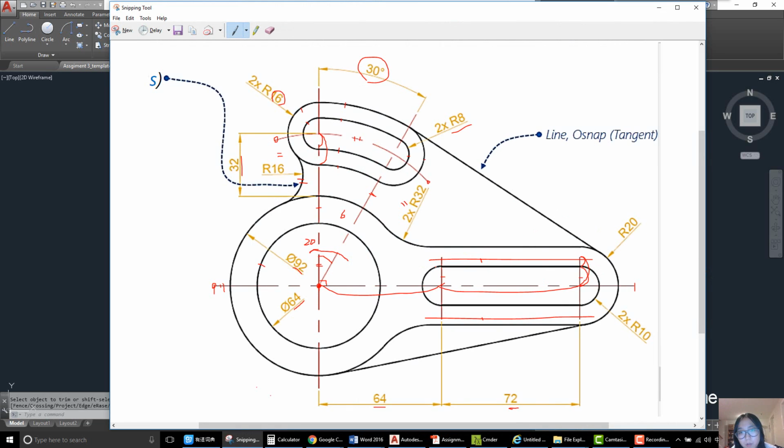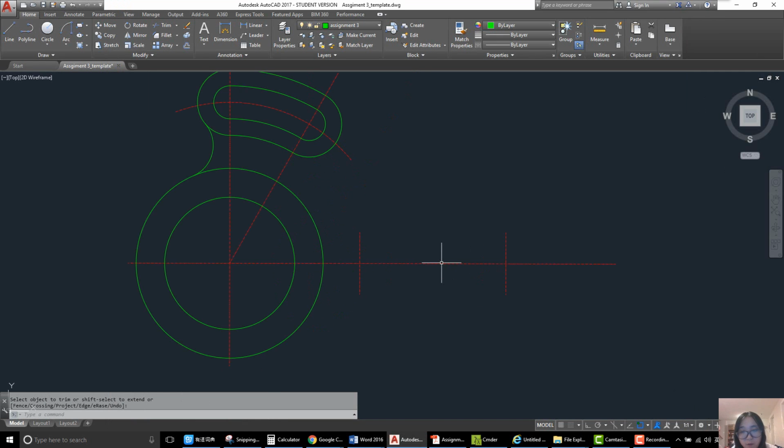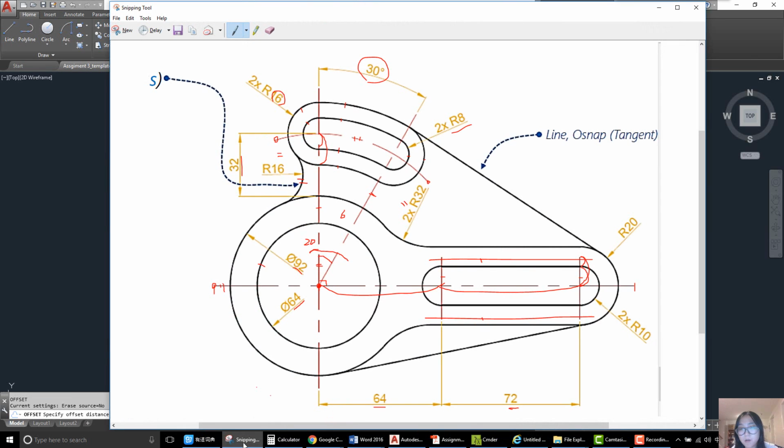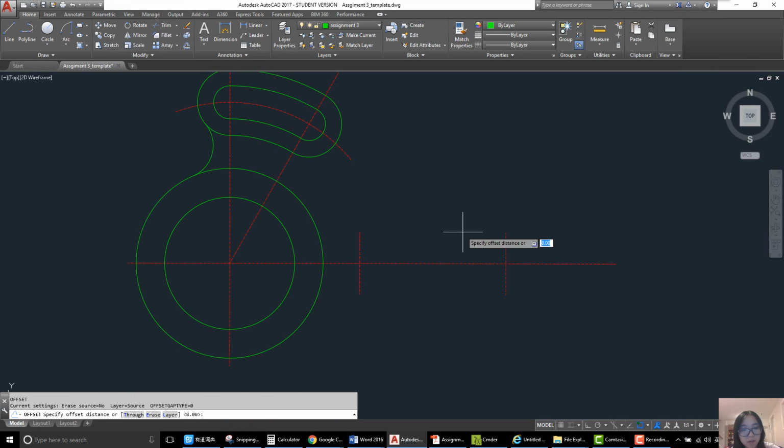Then I'm going to draw this inside geometry. I think, let me see. I can use line command to draw these two lines and the arc command to draw this. So, first, I will offset by 10 to upside to downside, and then